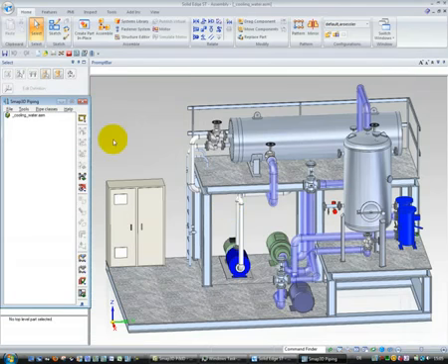So let's summarize the requirements that should be available before a user starts creating the 3D pipelines. At first there should be a 3D assembly as a Solid Edge assembly where all required components and equipment are placed and included. Then the library in the background must exist, and additional to that the pipe classes should be available for the end user. If all this is done, then an end user can start the 3D pipeline creation with the piping software.